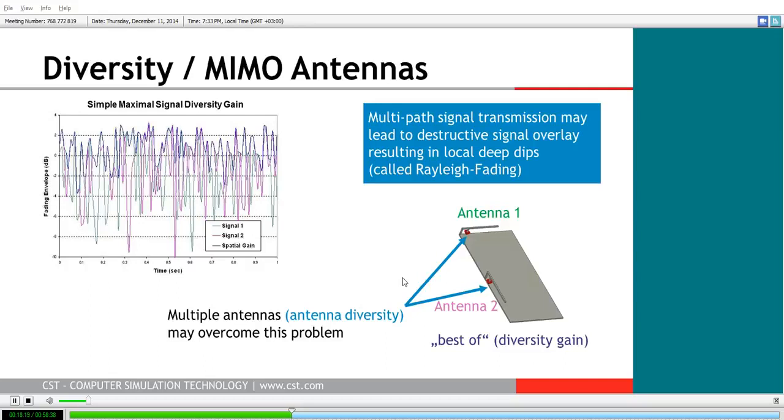And you can see in the resulting received signal, because we have these two relatively decorrelated signals, when one antenna is subject to a fairly large path fading dip, the other antenna is not, because it has low correlation. And as a result, the signal that we actually receive, we can opt between the best of the pair, and we get an effective gain from this diversity.